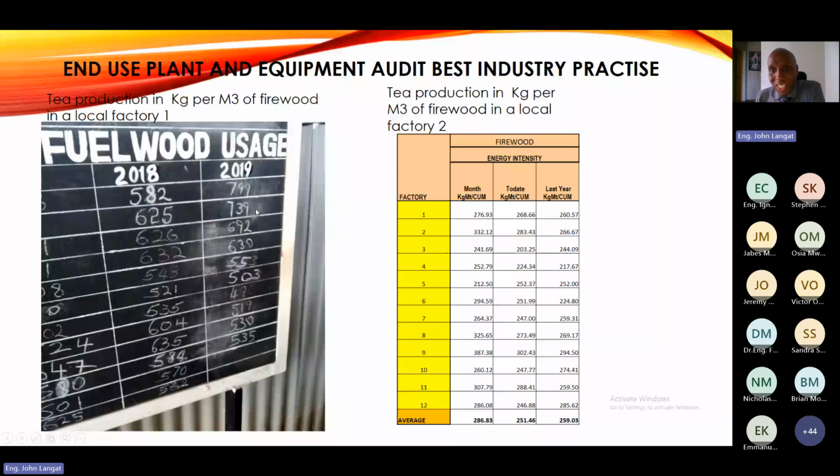While on this other one, these guys have only been doing on average 270, 300, 240, the average is 260. So you guys can see the trend. And if you see the setup here, this factory one, they had all what I've just discussed: an economizer, a deaerator, a limit switch for opening the boiler switch. Then they retrofitted the dryers to increase the number of radiator banks so that they fully utilize the amount of steam generated in the boiler, what I was just saying.